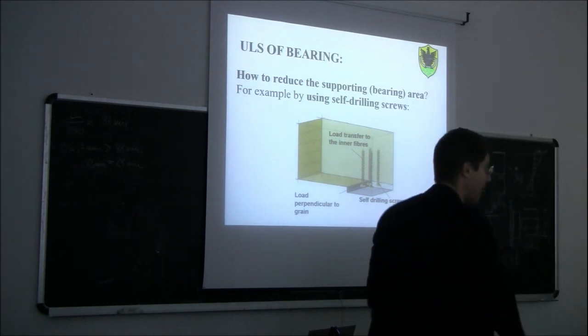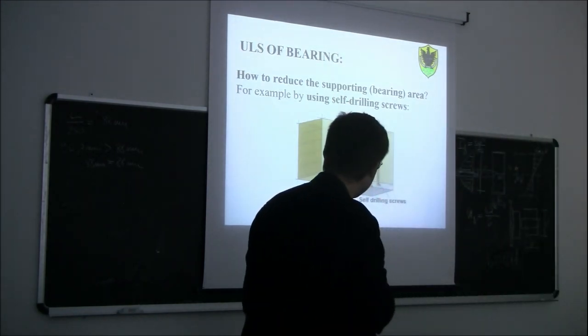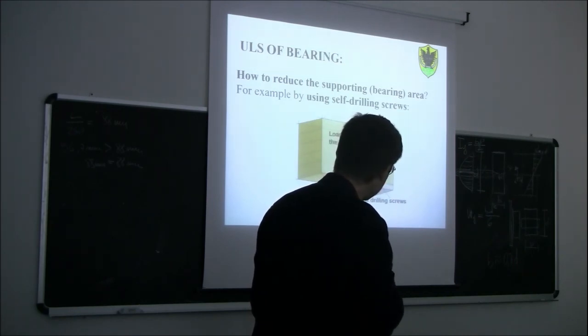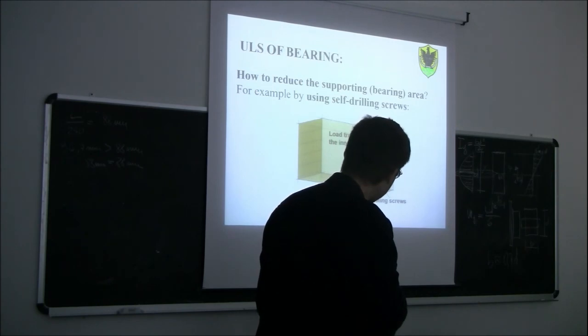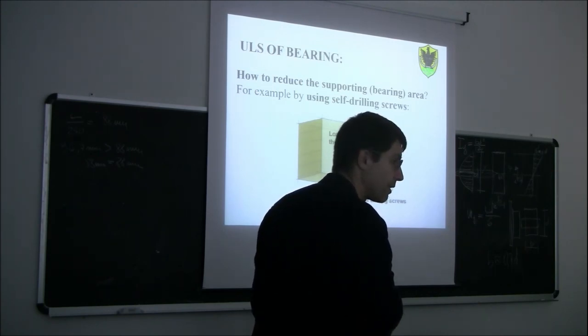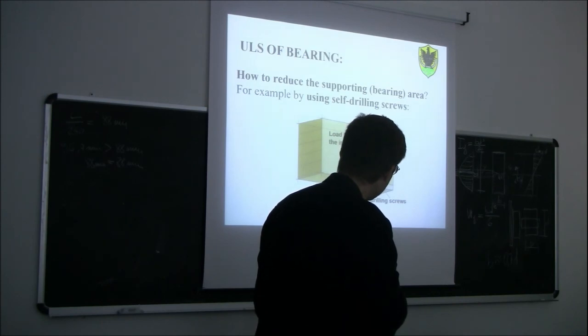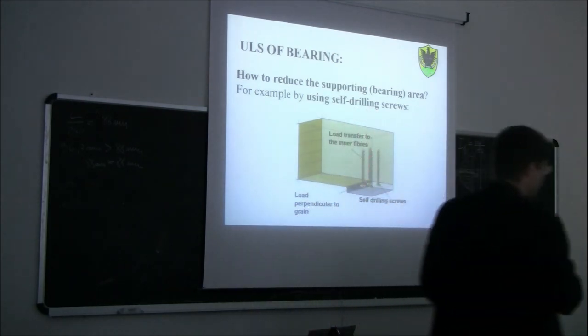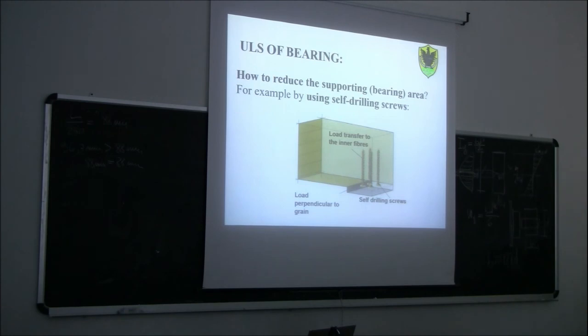So this is the idea behind here. If you put some self-drilling screws, those screws can in some way help transfer the load here, that is the extreme reaction, from the outer fiber to the inner fiber of the wood. So basically, this acts as a reinforcement, like reinforcement in reinforced concrete, which is going to transfer by bond, by friction, if you want, the load from this surface to the inner body of the wood.